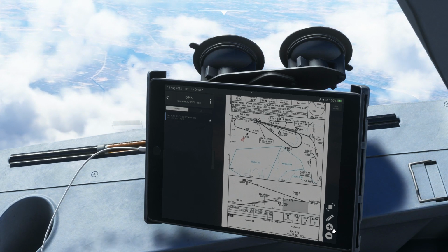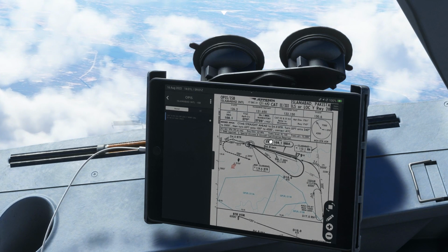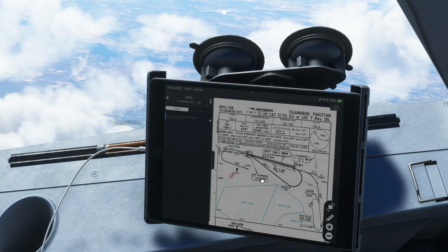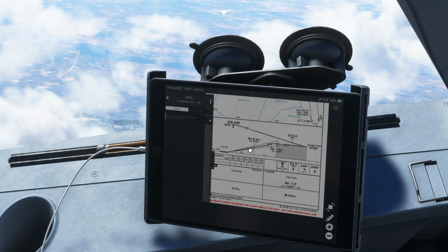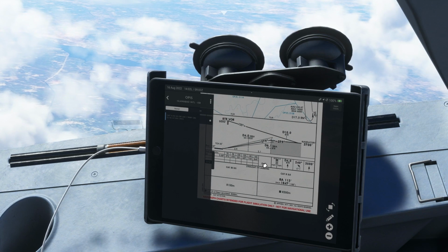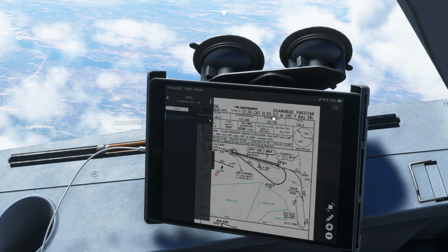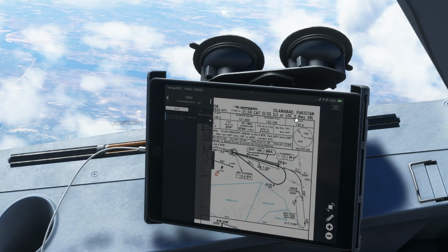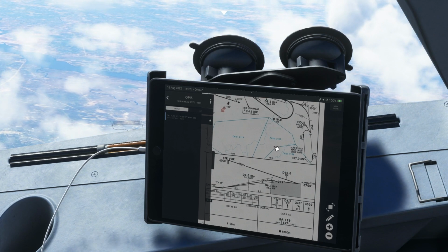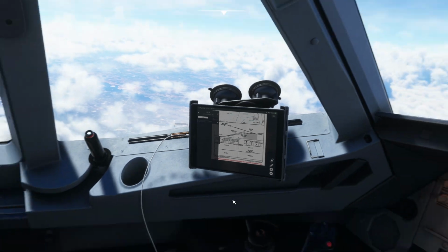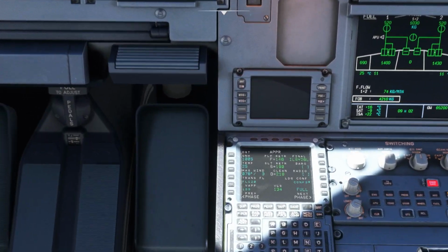So the decision height is actually, it comes over here. Yes, 1847. So if you're coming for ILS category 2 and 3, ILS LOC Y runway 28 left, the decision height is 1847. So let's enter 1847 over here.